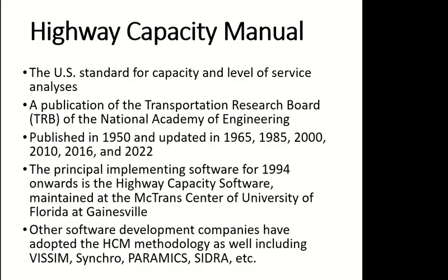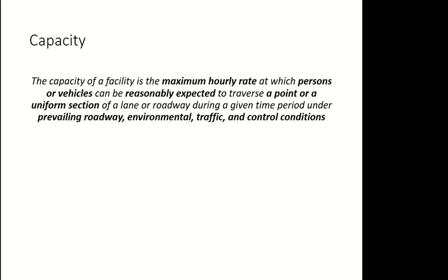The first software which was developed for these calculations was by a university in Florida, and this was to perform the calculations given in the manual. But now, any traffic simulation software you pick, for example Vissim or Synchro or Sidra, whatever, any traffic simulation software, their latest version will have or can help you with the calculations for capacity and level of service. So this has become very common now, but earlier it was a specialized software.